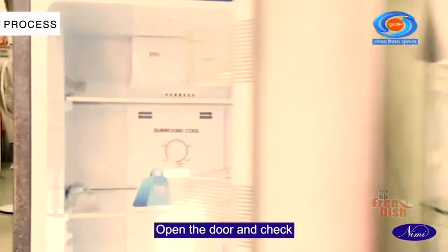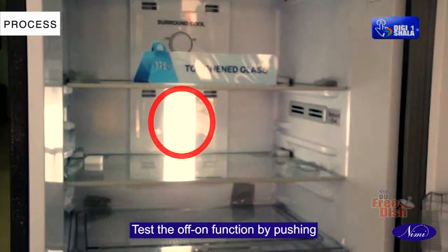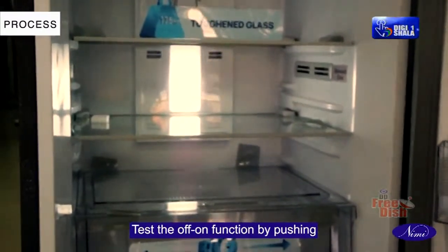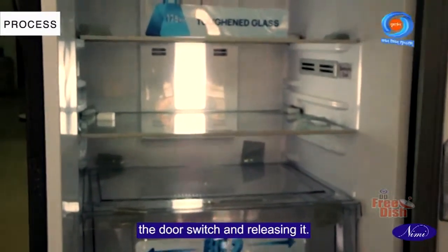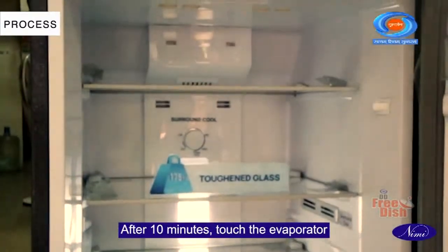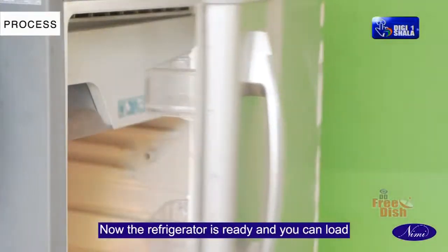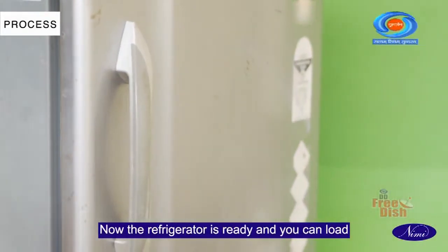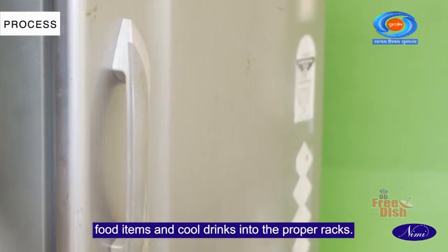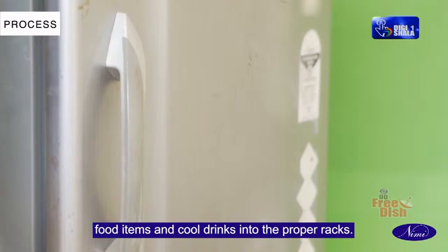Open the door and check if the inner cabinet light is glowing. Test the off-on function by pushing the door switch and releasing it. After 10 minutes, touch the evaporator plate and feel the chillness. Now, the refrigerator is ready and you can load food items and cool drinks into the proper racks.